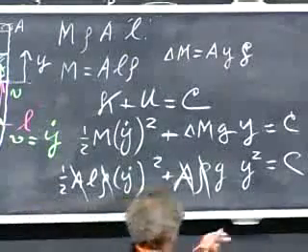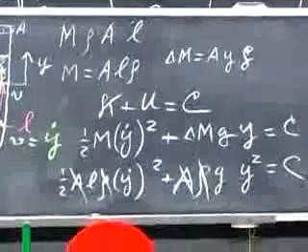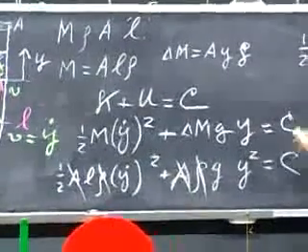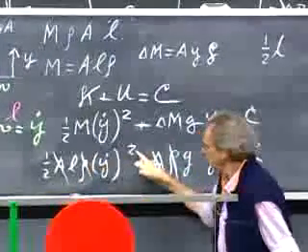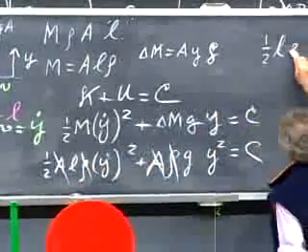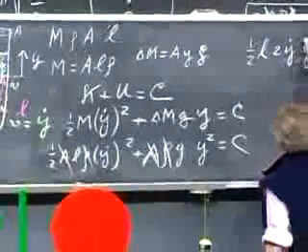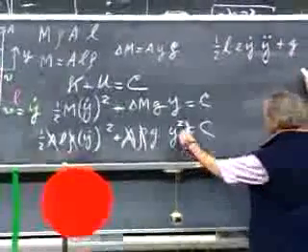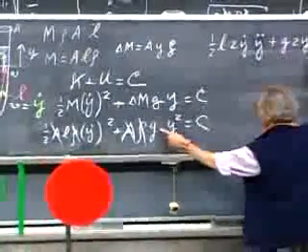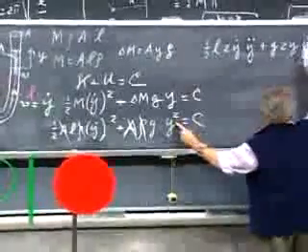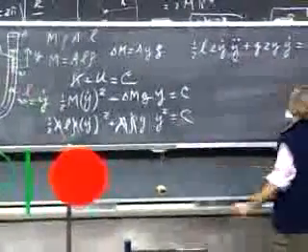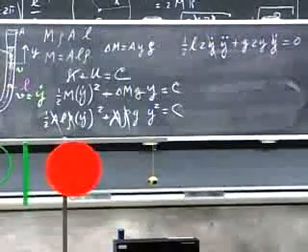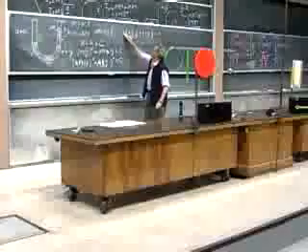And so we're going to take the derivative versus time of this equation. That gives me 1/2 L. The 2 pops out, and the 2 becomes a 1. So I get 2 y dot. Then I apply the chain rule, so I get y double dot. Here I get plus g. The 2 pops out, becomes 2y, and then I get the chain rule y dot, and that equals 0. I lose my y dot because I have y dot in both terms. This 2 eats up this 2.